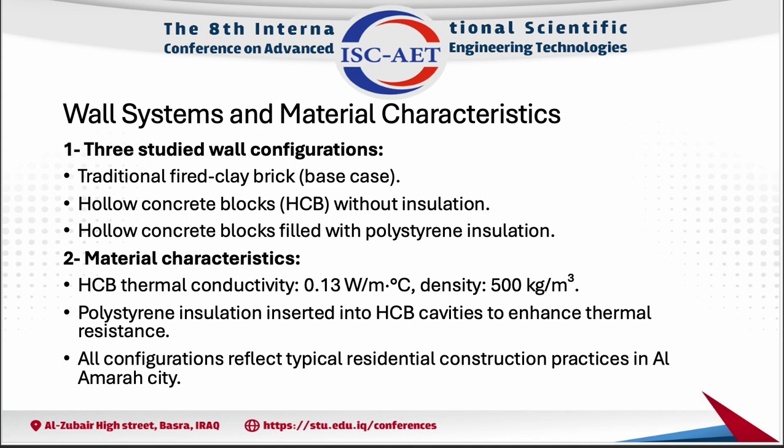For materials, the hollow concrete blocks used had a thermal conductivity of 0.13 watt per meter centigrade and a density of 500 kilograms per meter cubed. Polystyrene insulation was added to the hollow cavities to improve thermal resistance. These configurations reflect actual construction practices in Al-Umara, making the results directly applicable to real residential buildings.